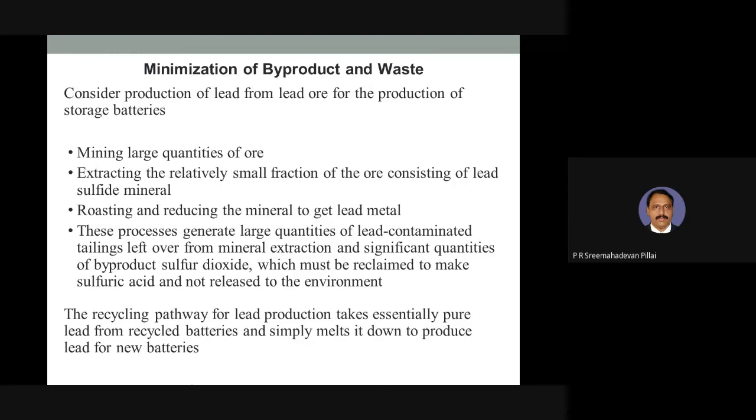So blast furnace slag cement is very common nowadays, and it also has higher strength, because this slag is basically of metallic content, but with some waste and some rust and all. But in cement, it adds strength. That is why blast furnace slag is very popular nowadays. Civil engineers will know it. We call it GGBFS cement, ground granulated blast furnace slag cement. You can get it in the cement shop. It will be written on the back of the cement bag: GGBFS cement. Okay, see the next slide.